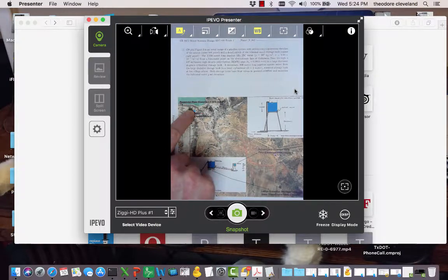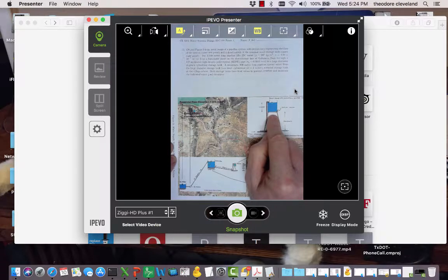to the treatment plant down here through a pump all the way up to the large diameter storage tank with a base elevation of 1,000.3 meters and a pool elevation of 1,006.3 meters, so 6 meters deep. It goes through a 127 millimeter diameter high density polyethylene pipeline with a sand roughness height of 0.0015 millimeters and to this large diameter tank, and then there's a secondary line 800 meters that carries water from the tank to the small terminal storage tank at the schoolyard.